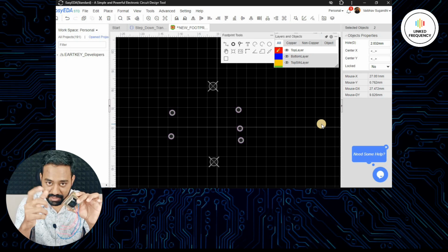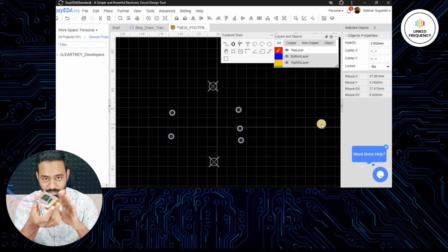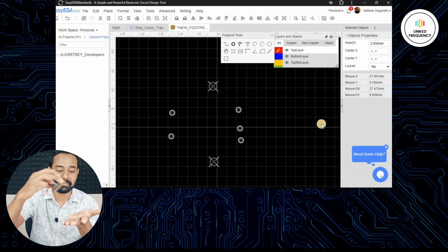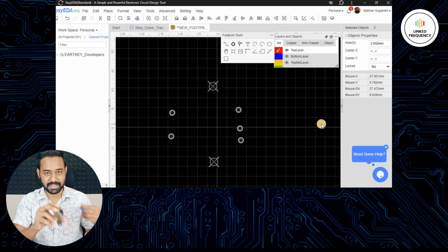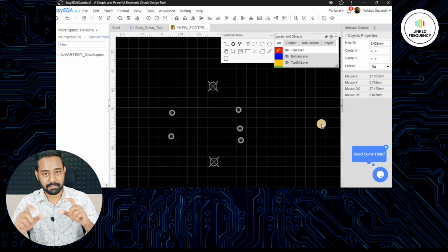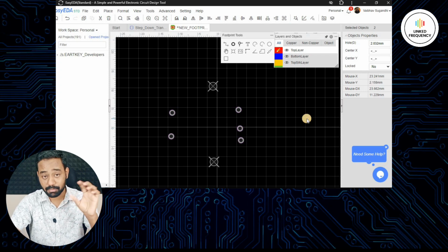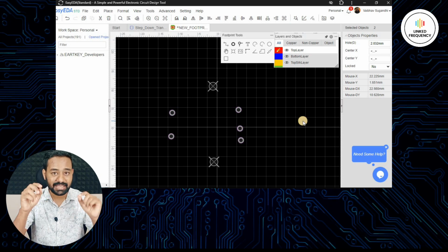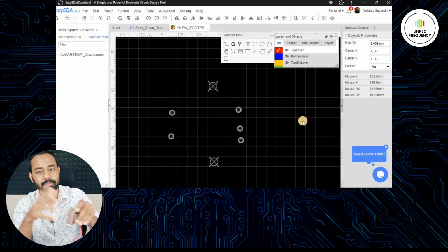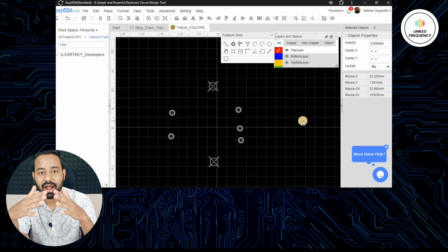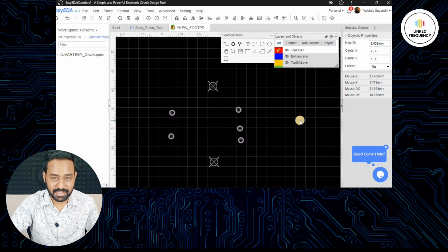This number looks very big because, according to PCB designing, these are very big. That's why I mentioned that these transformers should not be placed on the PCB directly. But right now, for the sake of study, we are placing it on the PCB. So 70 mm and 40 mm are the mounting hole distance and the body width of the transformer. Placing the connecting wire pads is up to us. We can place them anywhere after the 40 mm width of the transformer. So let's do it in EasyEDA.